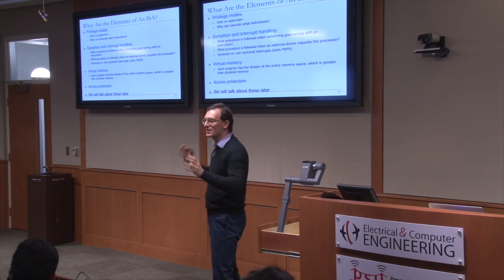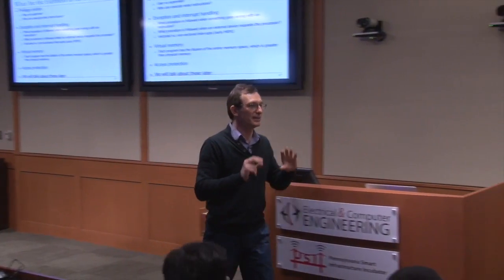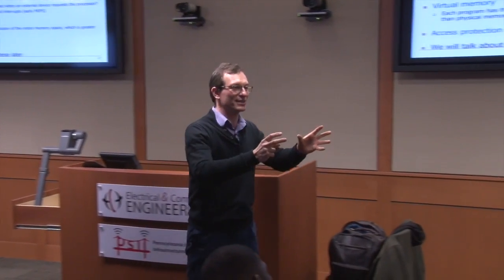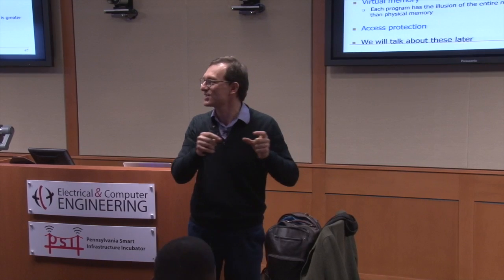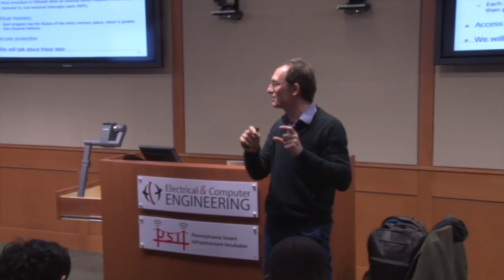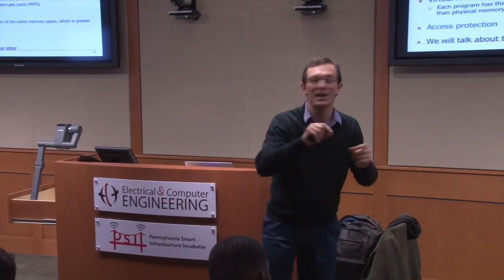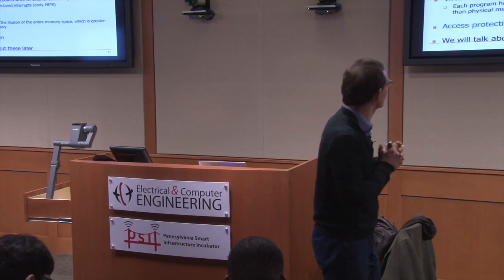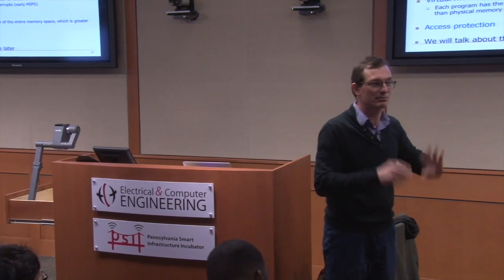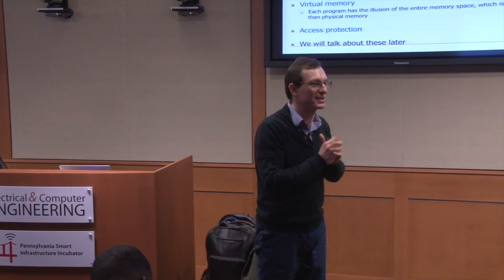So with a vectored interrupt, when a device interrupts a processor, it also writes, or somebody writes, which device is interrupting the processor in a register. This is called a vectored interrupt. Using this information, you can easily determine where to jump to service that interrupt, to the interrupt service routine. Non-vectored means this information is not available. The only thing you know is somebody is interrupting the processor.